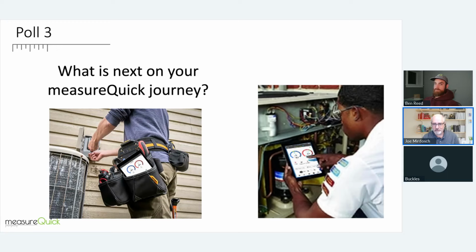The difference between a test out and benchmarking is I could benchmark it, and that's going to capture its personality, a variety of those conditions. From then on, all that information is saved for the next user, the next technician, or you when you come back out. I can see those parameters and see where it was, and see if my needle is still on my main gauges in the right spot, or if the system is not operating the same. Maybe I need to unbenchmark it, do diagnostics and re-benchmark it.